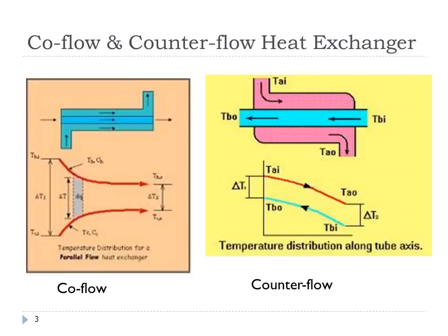This would be particularly the case in something we won't cover, but in solid oxide fuel cells. You may have a temperature difference between the hot and cold side of, let's say, 50 degrees, right? But the overall temperature increase from the cold inlet to cold outlet may be up to 500 degrees Celsius, from say room temperature to 500 degrees C, and that's only going to be possible if you're in a counterflow design.